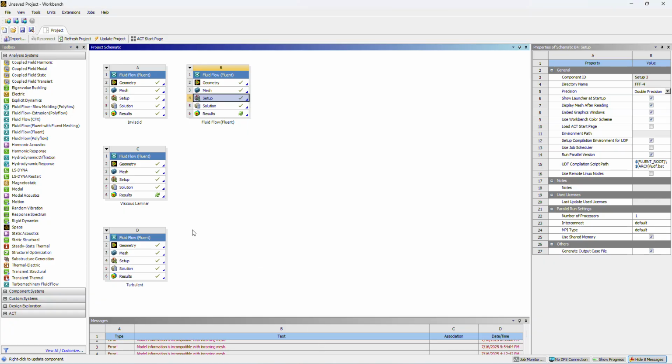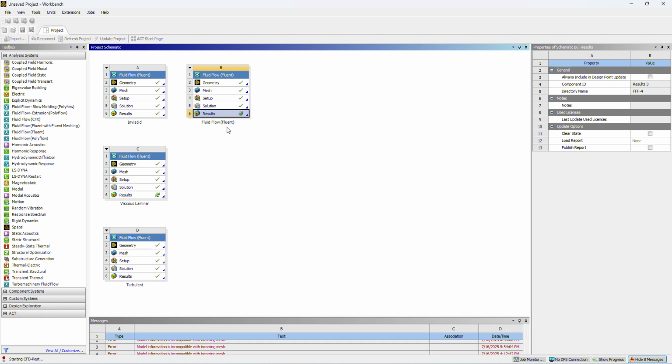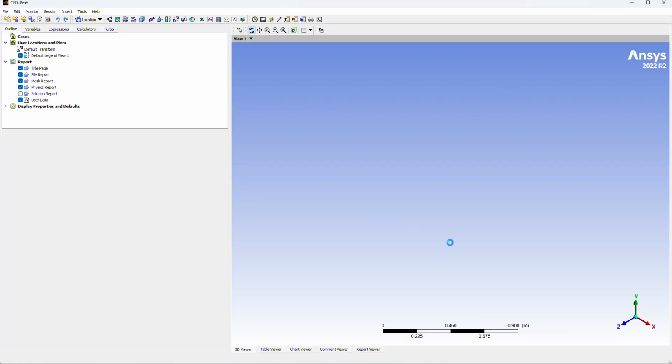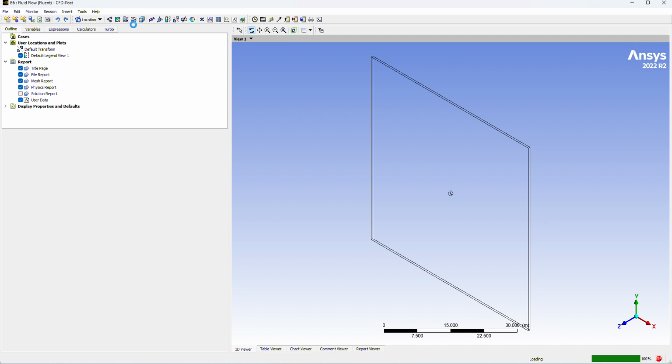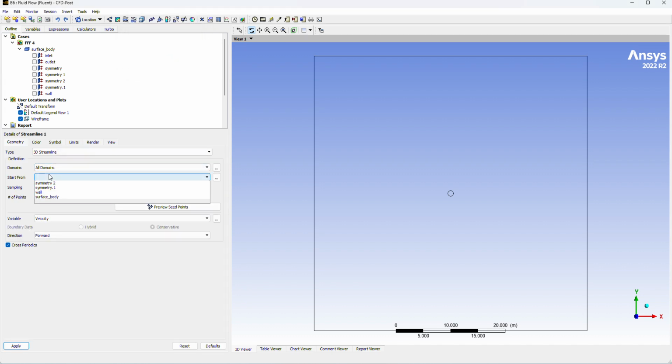And one of the other last things that we need is we can plot our streamline function to see the streamlines around the cylinder. Here this takes a second to load, but once it does, we will be able to go right up here, create our streamline, and we will start from the inlet, create a lot of points, and then apply.